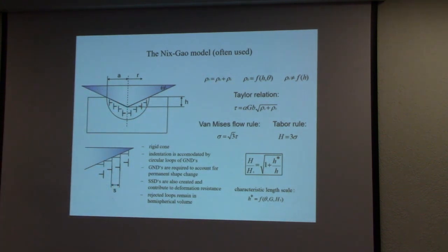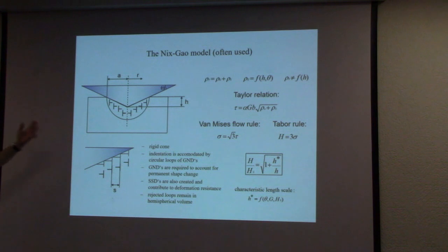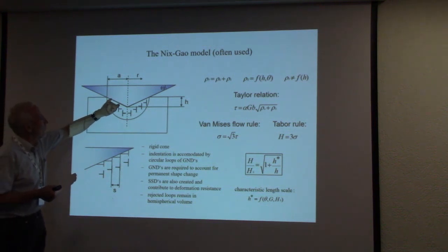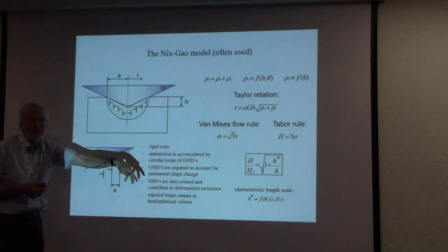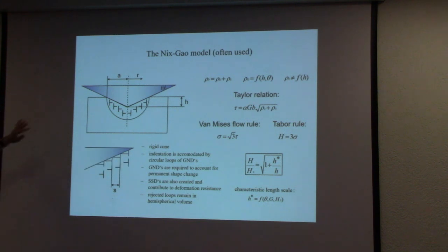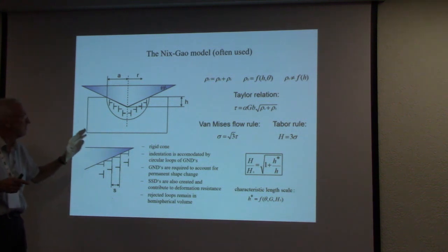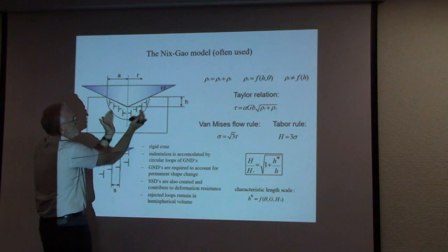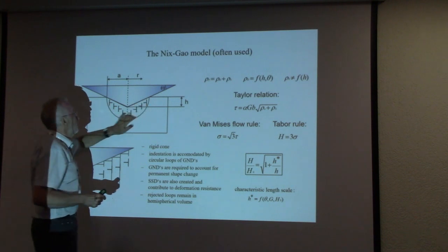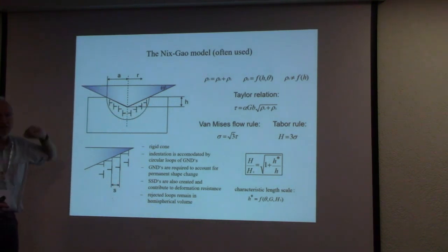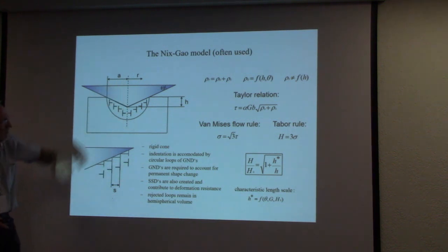And in order to realize this shape, we need a certain amount of dislocations, because in order to make all this shape change, we have to move dislocations downward. Or there exist different arrangements, but in all cases, we need a certain number of dislocations to realize this. And if we want to pack this in a certain volume, we have a much denser arrangement of the dislocations when the indent is small compared to a large one. That's easy to calculate.